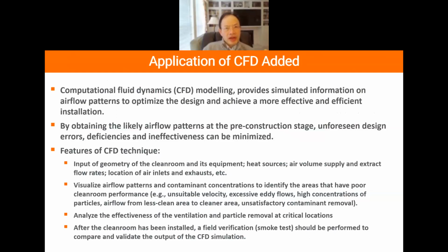So you can identify during the design stage that you may need to relocate a HEPA filter, add a HEPA filter, or add more filters. I keep the total CFM flow rate, but I distribute the HEPA filter airflow more evenly.